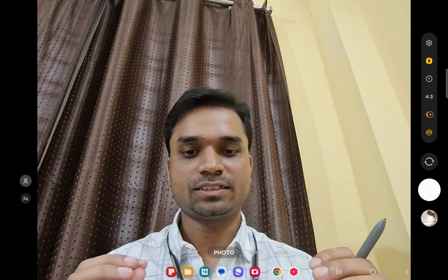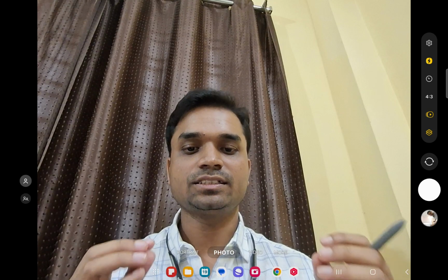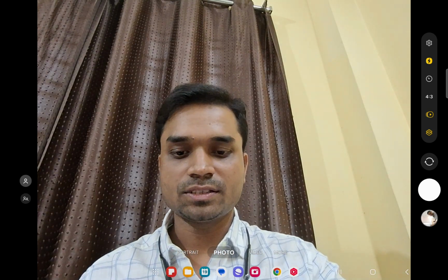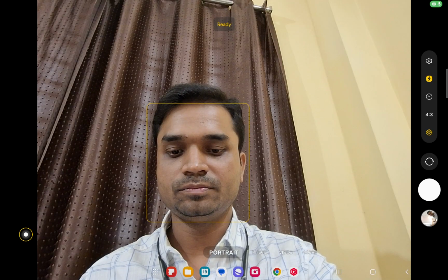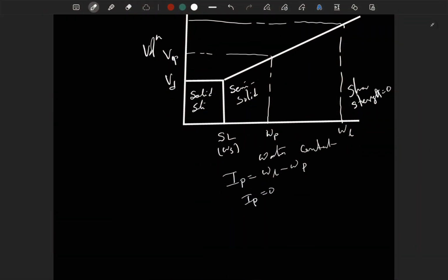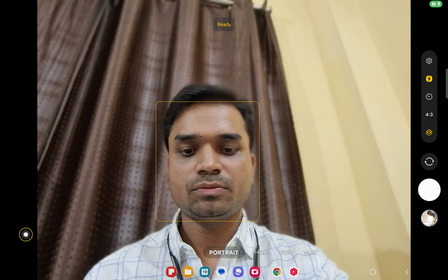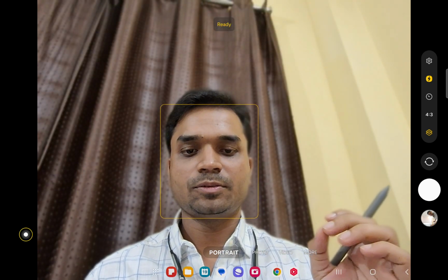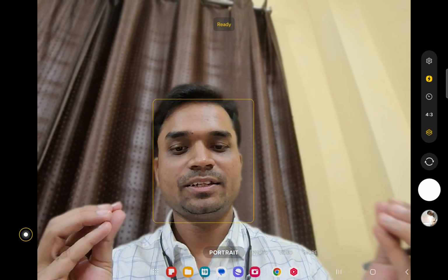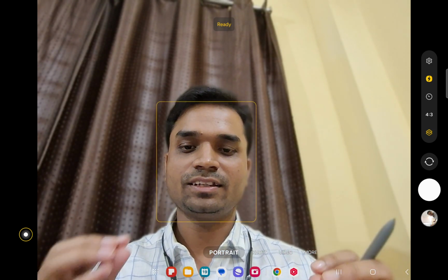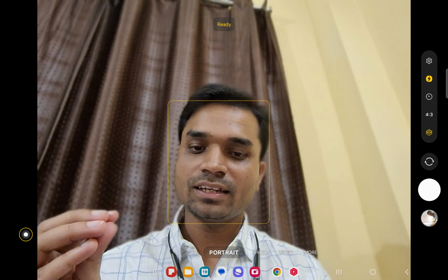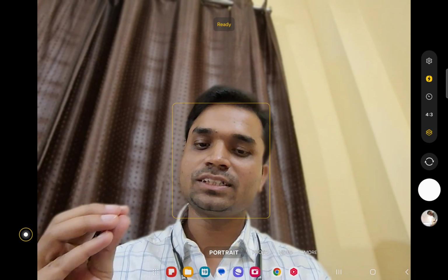And clay is plastic because it has IP. IP means liquid limit minus plastic limit. For the case of clay mixed with sand, the clay's liquid limit and plastic limit will be reduced.